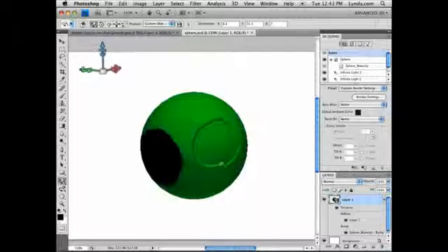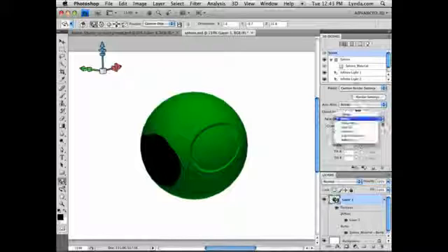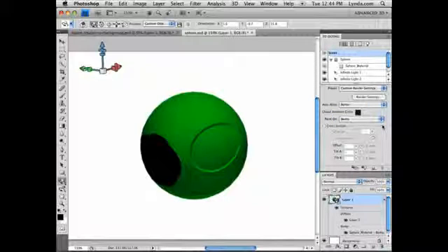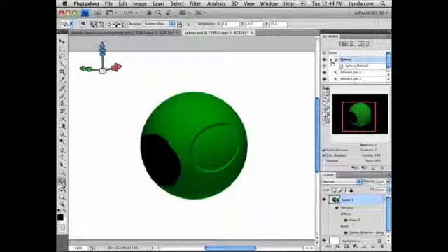You see that a little bit more clearly as I rotate that around. I'm still painting with black, but we've changed the Paint On drop-down. Photoshop's powerful painting engine can also be used to directly alter opacity, reflectivity, self-illumination, and other attributes. To get a closer look at an object's materials, we can click these squares in the Scene tab in the 3D panel. These represent an object's materials. We could also click this disclosure triangle to collapse and expand individual objects. That can help to keep this panel organized if you have a lot going on in your scene.